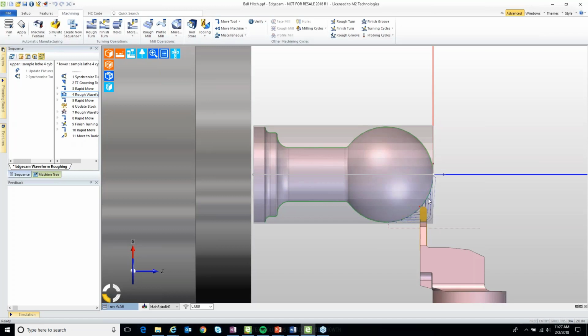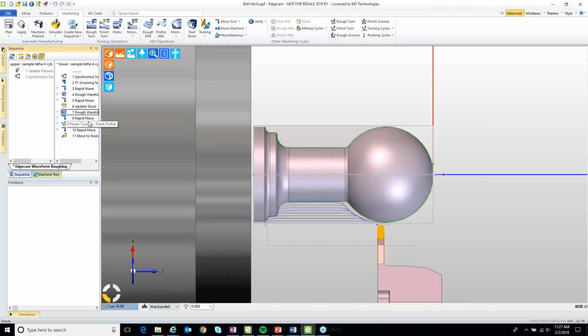The next cut picks up at that point, and now the tool is allowed to run both directions to remove the material from this captured area. There's only really one way to get into here, from this direction, and this is technically a groove application. With one tool, we're able to machine both segments of this part.